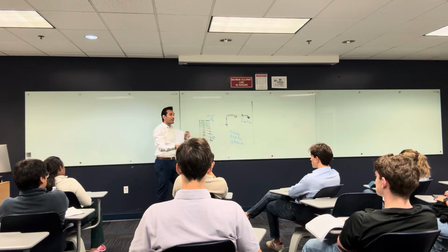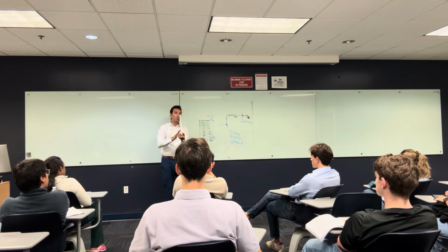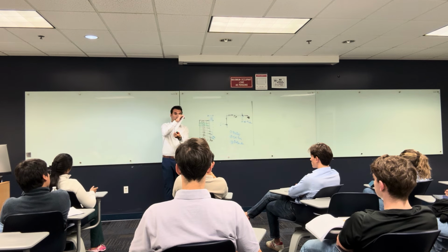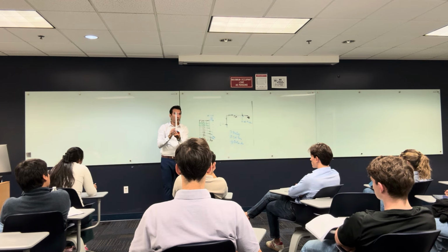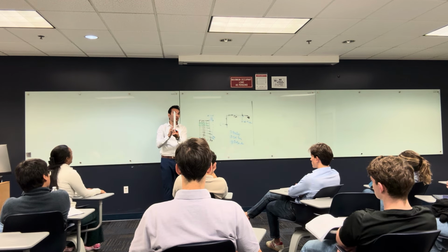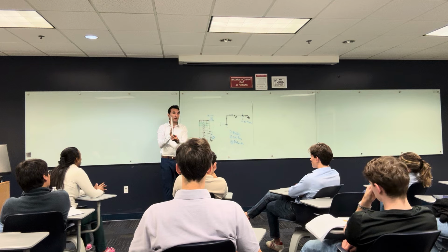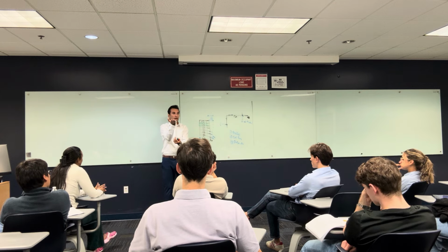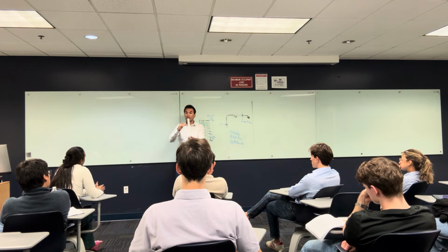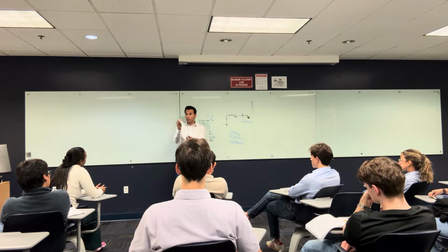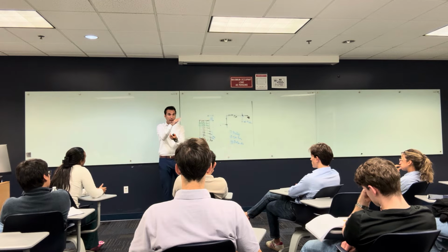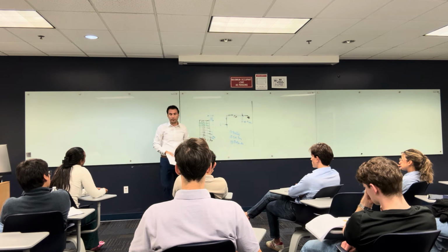So the mass is the source of the load on the lateral load system that you have. The more the mass is away from the ground, the more it is going to make this building bend that way. So the masses at the lower elevation contribute less to the loads on the lateral load resisting system, and the ones at the upper elevation contribute more to the loading, all right? So that's what happens, and you keep getting thrown that way.